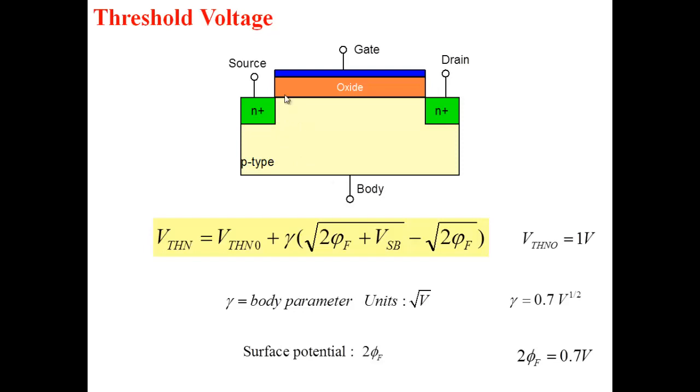Our interest is, when I'm using a MOSFET, our interest is in this current here, channel current here. Any extra current, any other current is, unless you want this current to flow, okay? But most of the time, what we are interested in when we are using a MOSFET is this current here. And so our interest is that all other currents should be negligible. So you can reduce the threshold voltage, but you are in sort of a danger territory. If you're not careful, you may bias the source body junction too much and start getting unwanted currents into the source here.